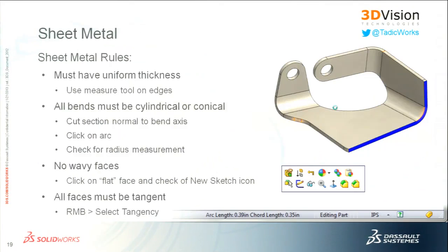Would that preserve the hole wizard callout in the drawing of that part? Yep. Good question. The question was, would that preserve the hole callout on that feature? And yes, it would. You can actually modify the holes. I didn't necessarily modify a hole. I copied that surface and made a cut near the hole.